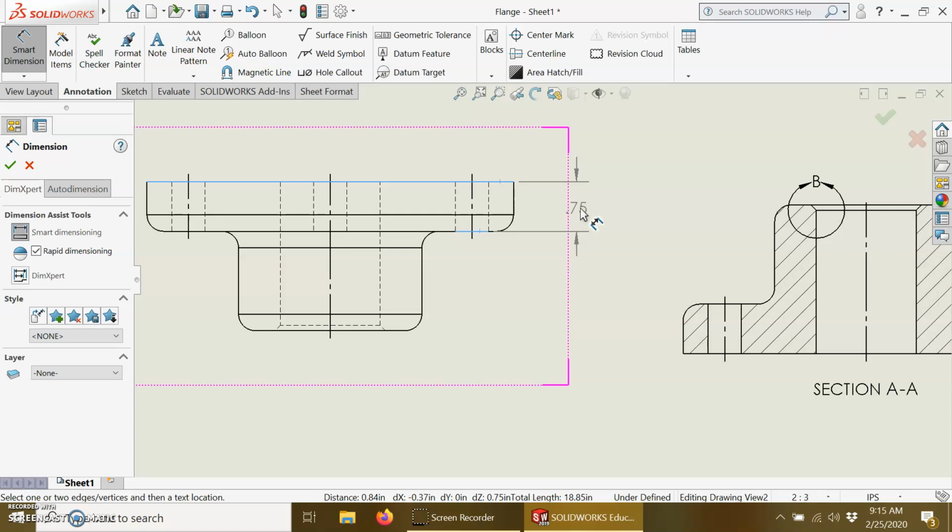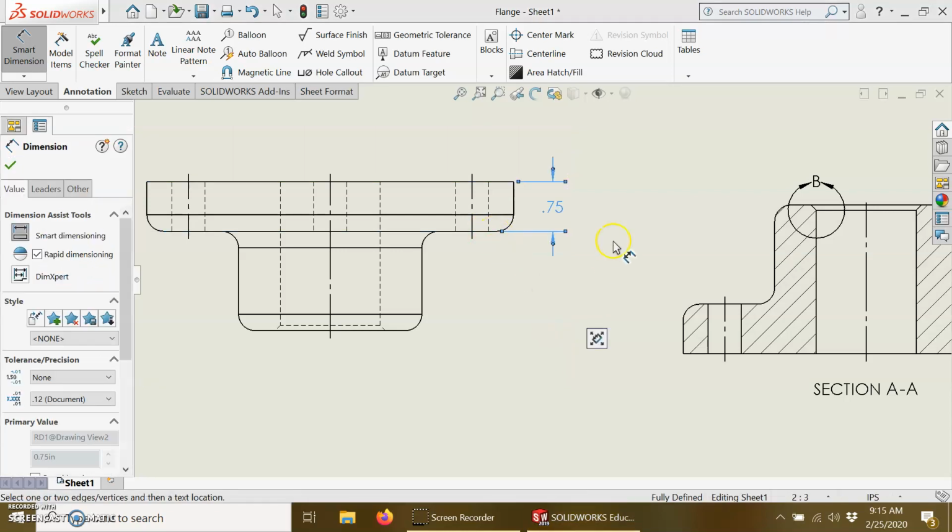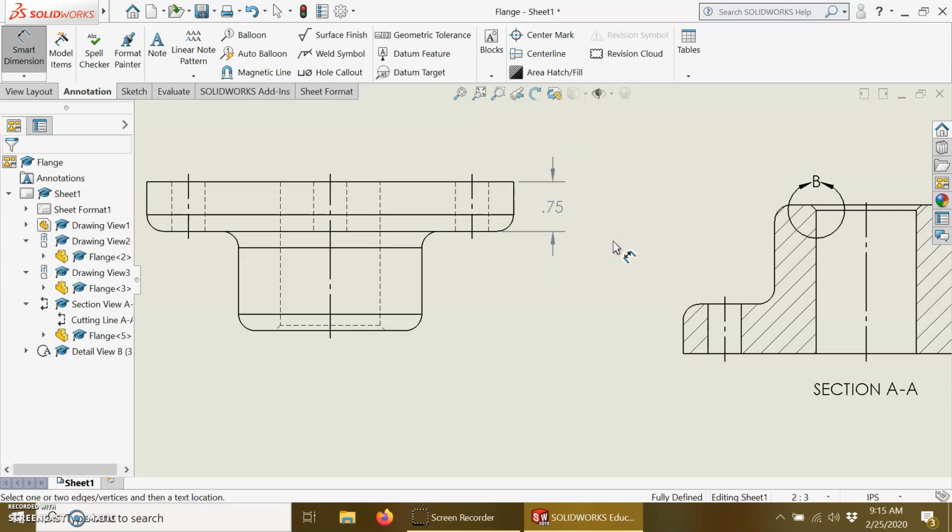So the way dimensioning works, detailing with the ANSI standards, is basically everything's supposed to be clear. Everything's a set distance away from parts and whatnot. Everything's kind of centered. So you'll notice that when I originally clicked this other guy here, you see how I've got these two little half circles here. That's part of the quick dimension formatting. It's saying I can either put it to the left-hand side or the right-hand side. If I just click on that, that drops my dimension where it should be. It centers it, it makes things look pretty, and things are not going to overlap.